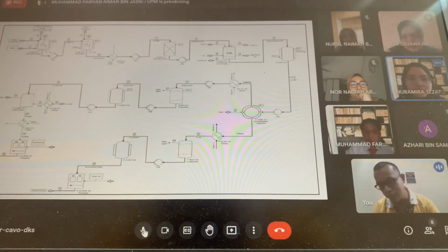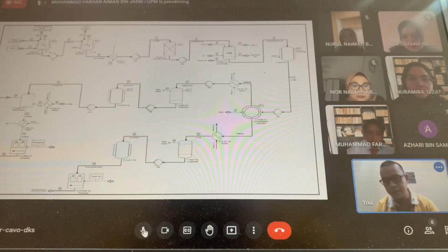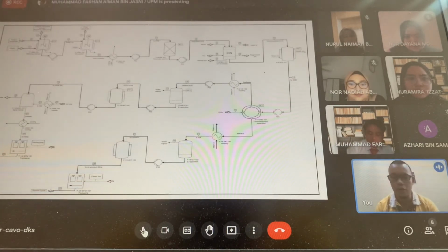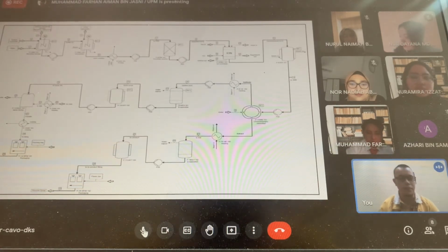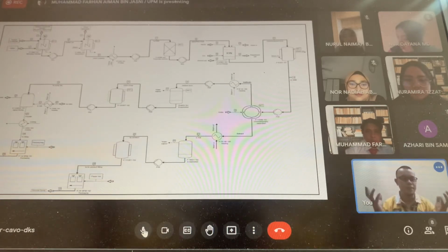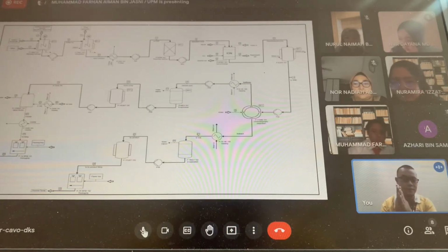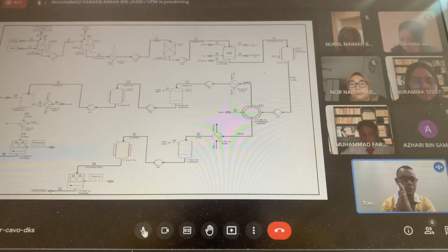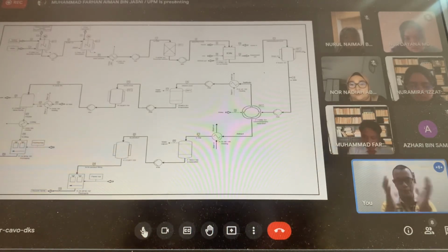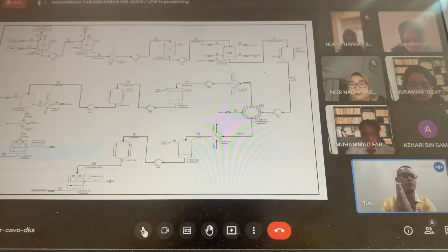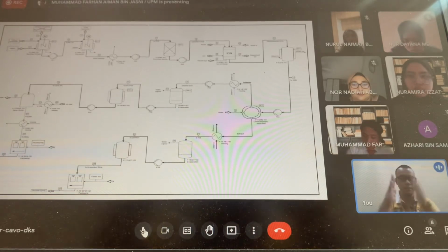Yes. Okay, based on your PFD, you don't have what we call a hopper load cell. There is a load cell where we measure the powder when it goes inside before it reaches 10 kg. How do you measure 10 kg of powder in every bag? You cannot measure, you don't mention it here. So I explain the process here. When the last process goes to before the bag or pouch, there is what we call a load cell to record the weight.